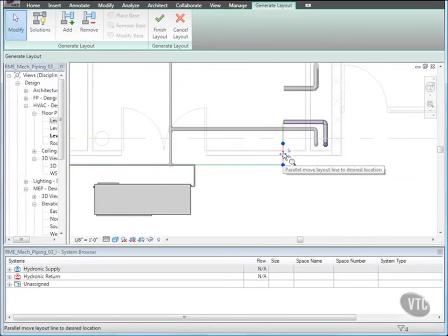Then, while holding Control, select the vertical sketch line just above it. Then, click and drag the 4-way arrow control to the left, just to the right of the double door in the underlay. Then, select the short vertical path line connecting the right heat pump and drag it to the right to align it with the sketch lines you moved.